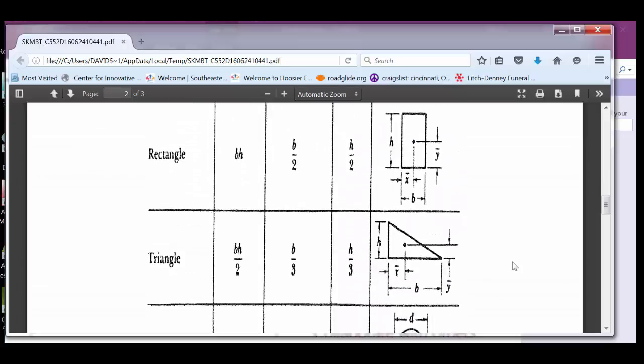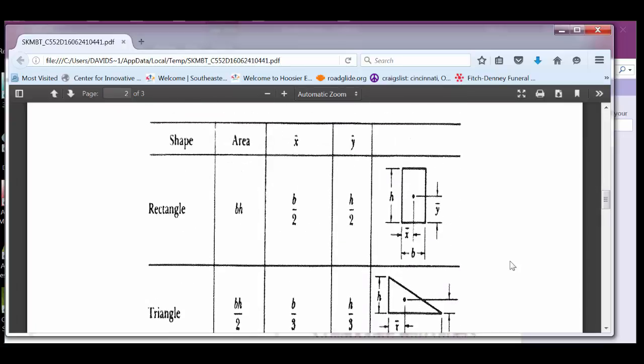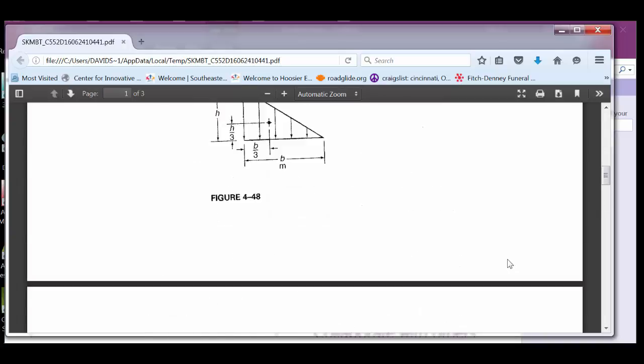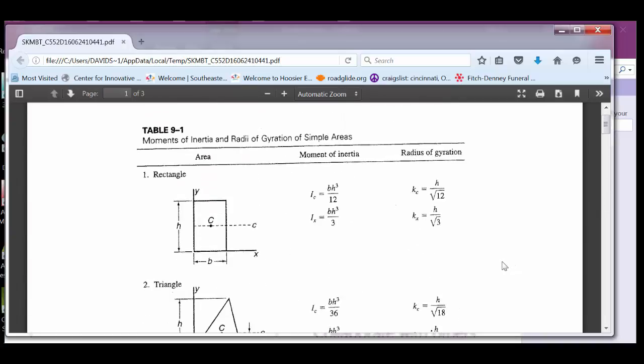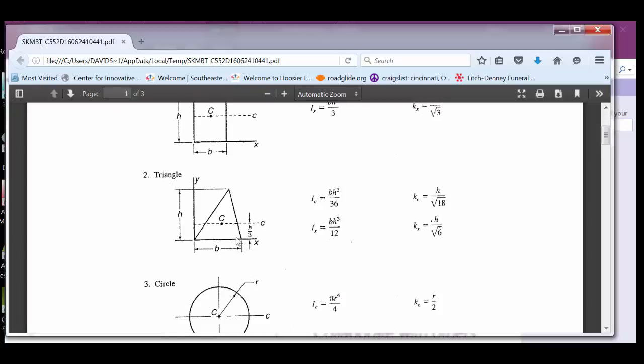And this sheet will be dealing, you first have to find the center of gravity, then you use that to help calculate the moment of inertia. Okay, so we have to find that point where these different shapes would, if you stuck a pin through there, just spin freely and be, if you will, balanced.